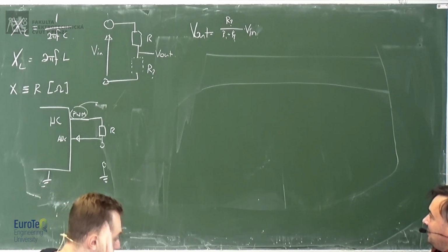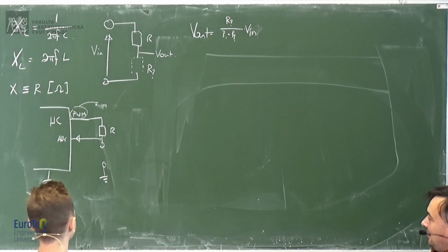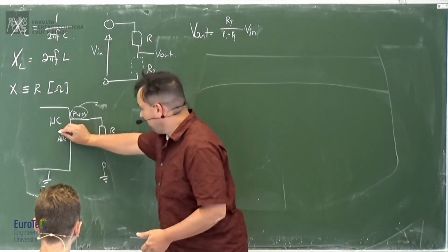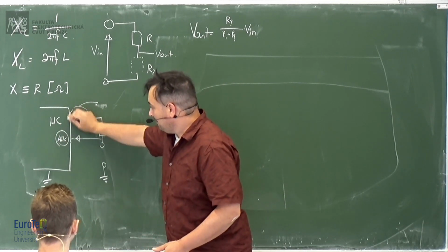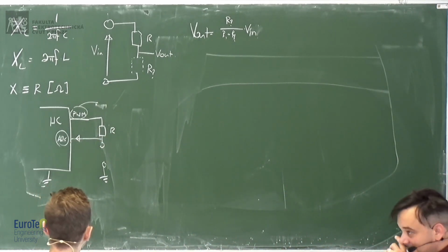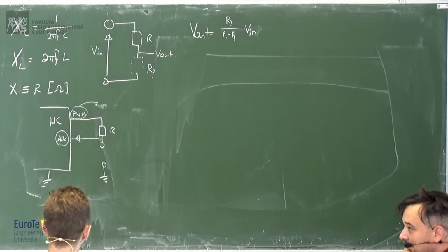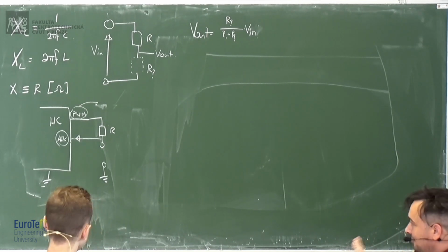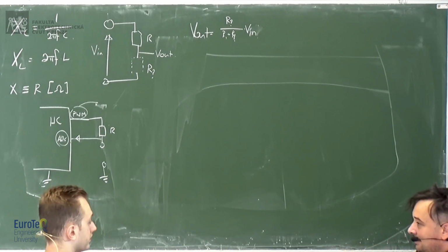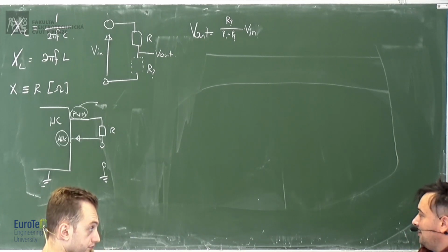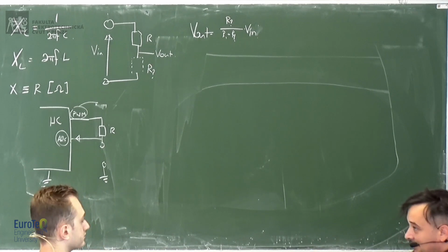The point is that first of all you have to understand what you get here. You get a voltage, yeah, but then you make some demodulation internally, because the voltage will change if you had PWM, right? Probably a low pass on the output or the input. So you can make a digital demodulation, which is what is done in that chip I was talking about.